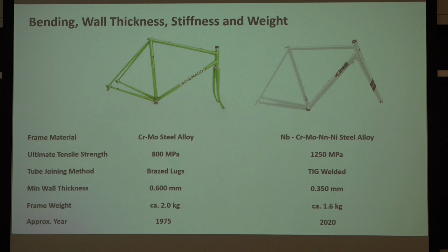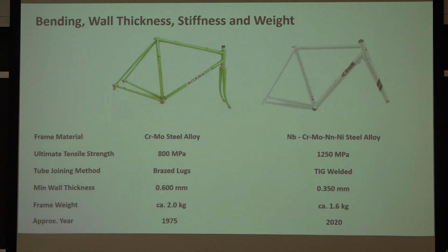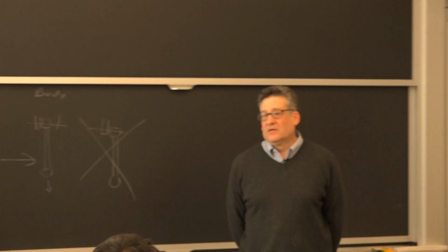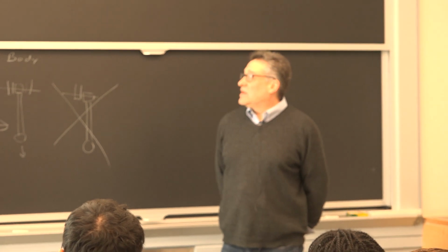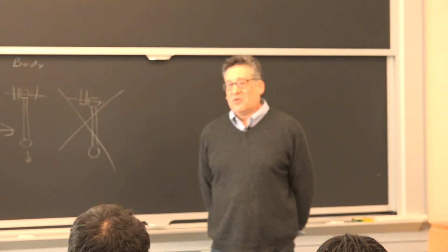Yeah, so I guess you can continue increasing the diameter, and then you get more stiffness, but is the limiting factor besides material torsion? So there are portions of this frame that indeed are under torsion. You're absolutely right. The real limit here is actually how thin can you go.